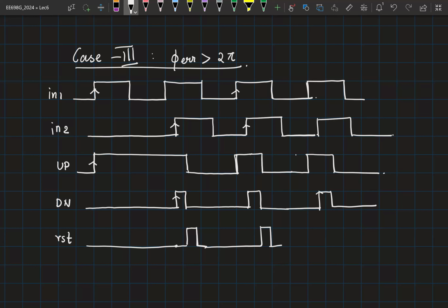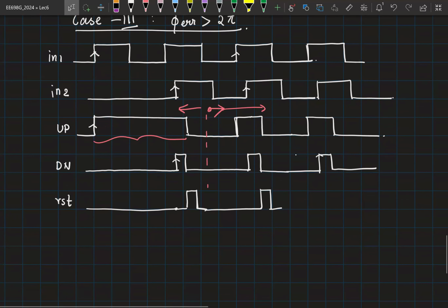Right? So now if you look at it, it looks like the up and down signals have something happening over the first period, and then a totally different pattern throughout after that. If I'm observing this waveform for a long time and then taking the average value after it has achieved steady state, this is like a transient, right? So this will not affect the average if I observe it for a long time. We are interested in the steady state average, so you take the average beyond this point. Let me consider one period after this. So let's say I consider one period like this.